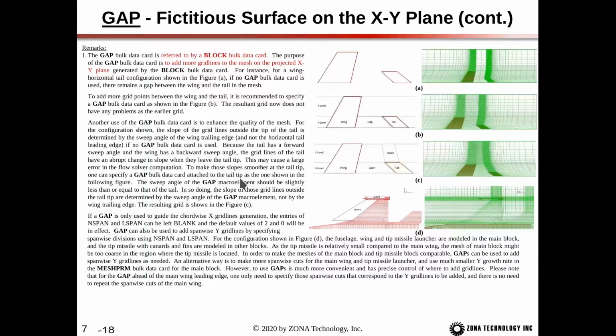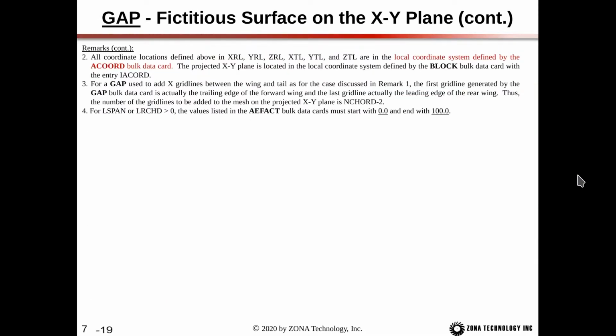And I think I've covered everything in the remarks here. Just further note here, all of the coordinates in the XRL, YRL, ZRL are in the local coordinates defined by the ACORD card.